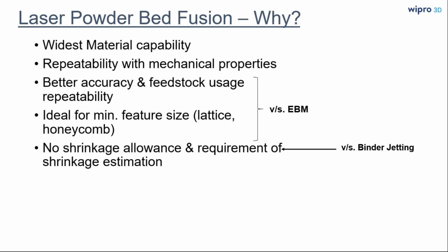So when we compare it with electron beam melting, yes, it's definitely less aggressive, and we have a better throughput when we are working with materials like titanium or stainless steel and aluminum. Aluminum definitely cannot be processed using electron beam technologies because we are working with temperatures exceeding 1000 degrees, and the melting point of aluminum is somewhere around 600, 650 degrees Celsius.